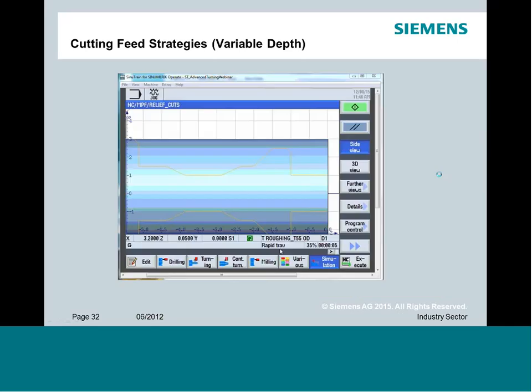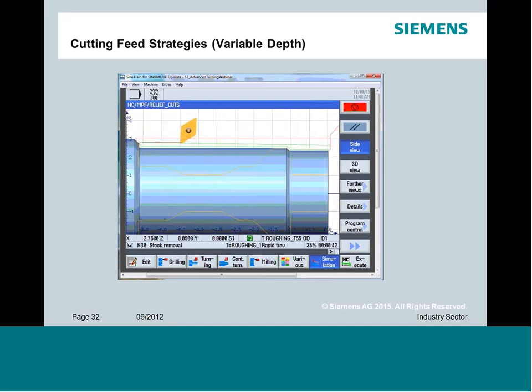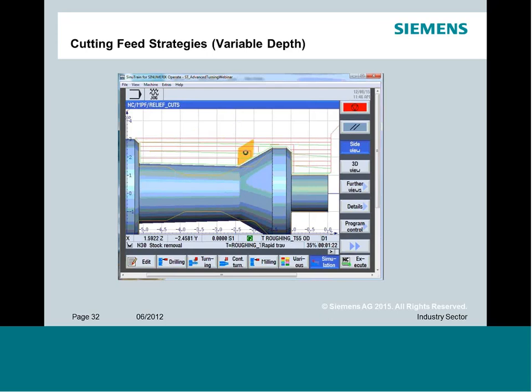So what is the actual cutter path going to look like? Well, if you look here, the tool is going to come down, and now you're going to see that first cut's actually an angle, and then I'm going to get a straight cut, and then I'm going to get an angle, and a straight cut, and this is your varying. So now it's changing that tangency point on the insert. Now you may get an extra cut or two depending on how all the values stack, but you're going to dramatically increase tool life, especially if you're experiencing this type of wear on the insert. It's going to reduce that potential.